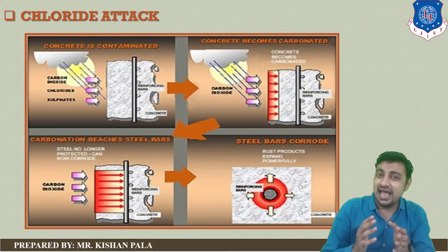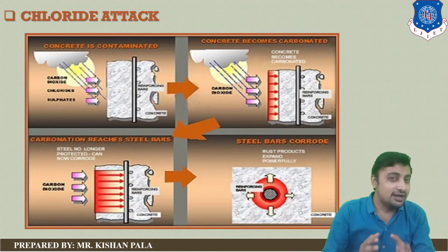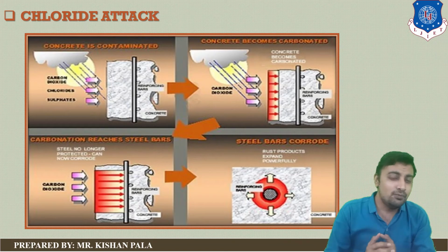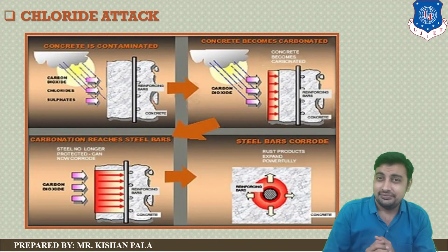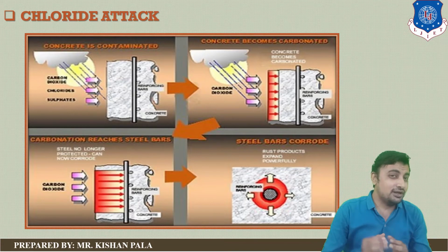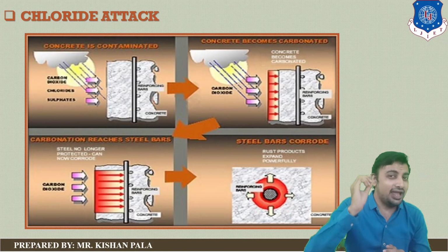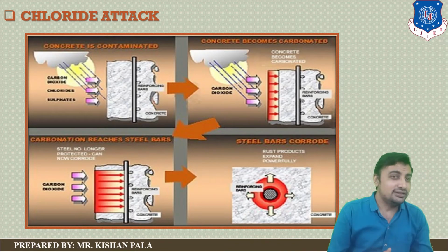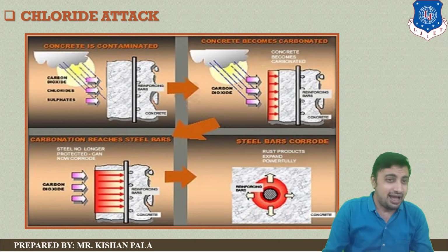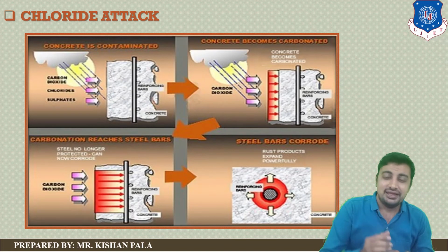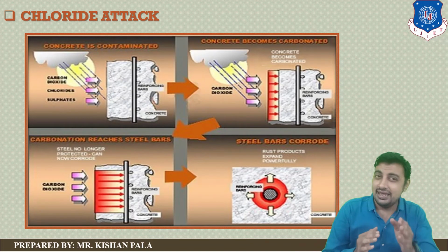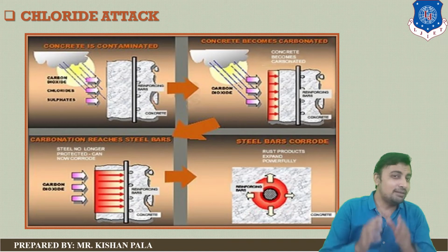When de-icing agents are applied to concrete of a few weeks' age, the damage would be severe. To protect such concrete, boiled linseed oil diluted in equal part with kerosene or spirit is applied to the dry surface of the concrete in two coats. The layer of oil slows down the penetration of the de-icing solution.